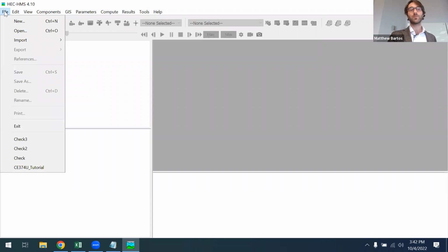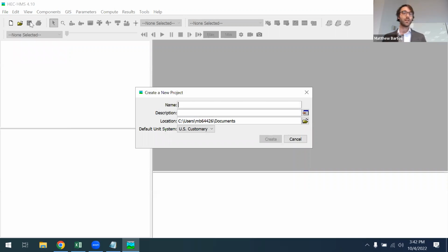The first thing we're going to do is go to File, New, and create a new project. So I will just call this CE 374U in class tutorial. Description, we can enter any description we want. We're just going to say my first tutorial. Okay, and under location, you can just pick any location on your file system you're comfortable with. For default unit system, we're going to use US customary. So let's go ahead and create.